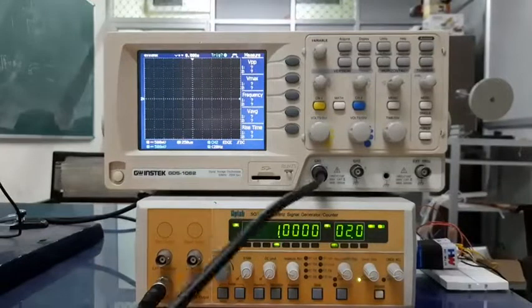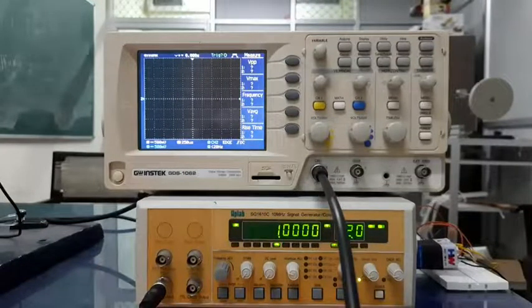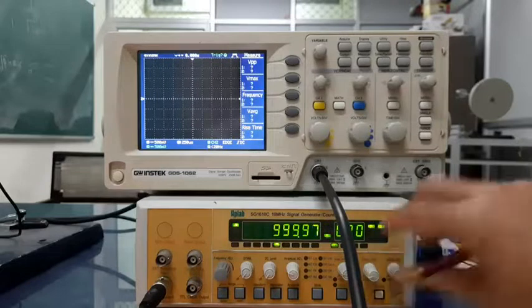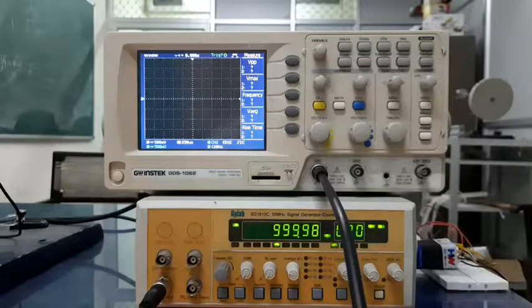Now, as long as my function generator is giving me an output of a 1 kilohertz, 2 volts peak to peak sine wave, I should be able to see it on the monitor. But we do not, because we have not yet set the parameters correctly. So now let's go over these steps, which are the primary steps one needs to know to see a signal. I would recommend that, if possible, you write down these steps, and every time you work with an oscilloscope, you go over them to begin with, and slowly you will become habitual of doing it.